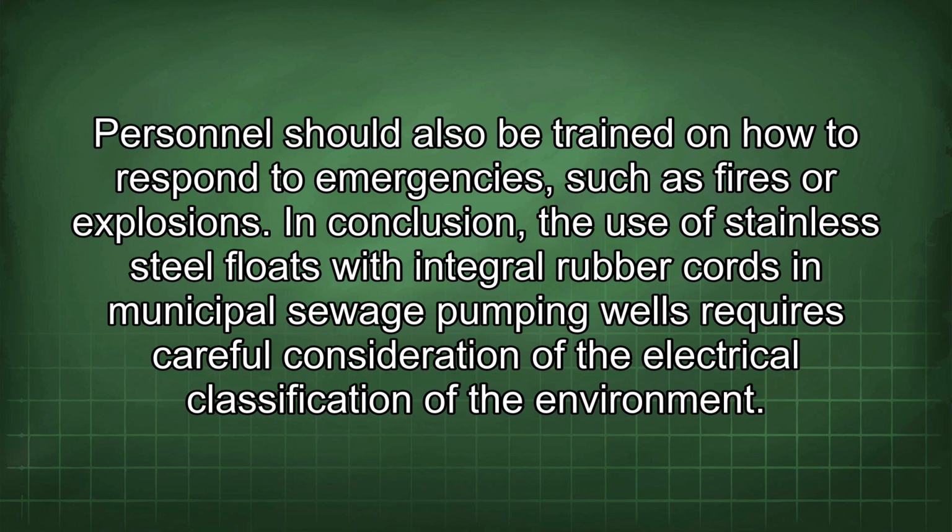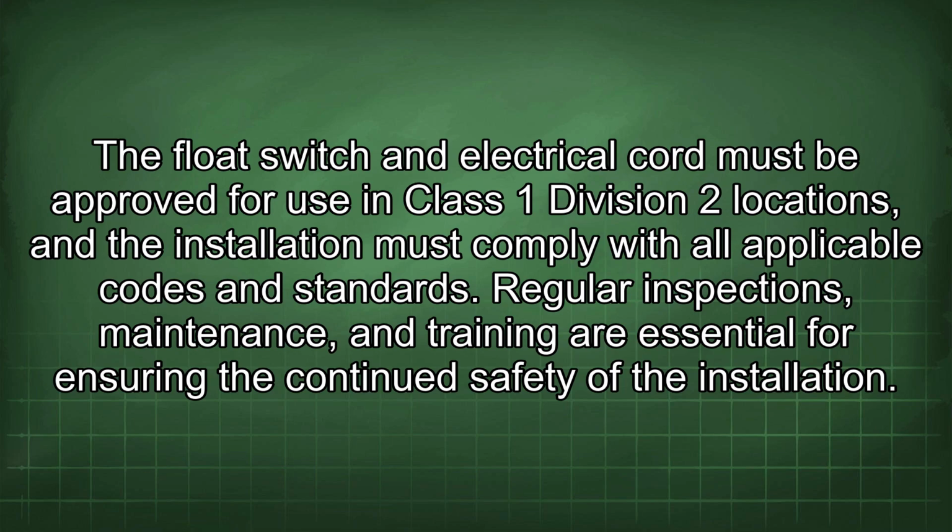In conclusion, the use of stainless steel floats with integral rubber cords in municipal sewage pumping wells requires careful consideration of the electrical classification of the environment. The float switch and electrical cord must be approved for use in Class 1 Division 2 locations, and the installation must comply with all applicable codes and standards. Regular inspections, maintenance, and training are essential for ensuring the continued safety of the installation.